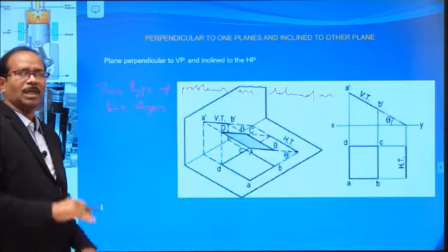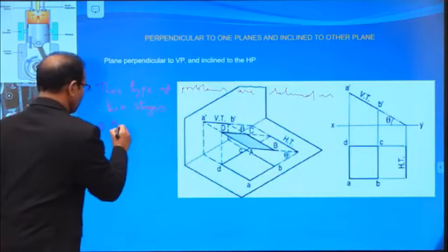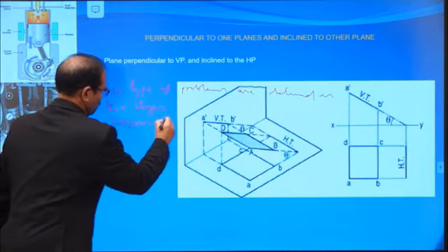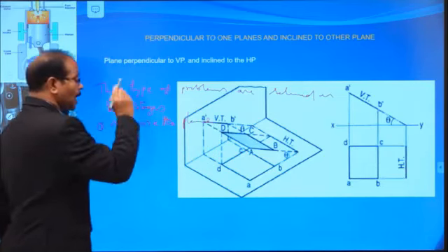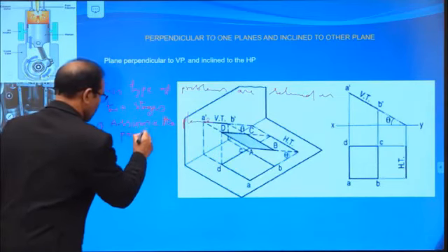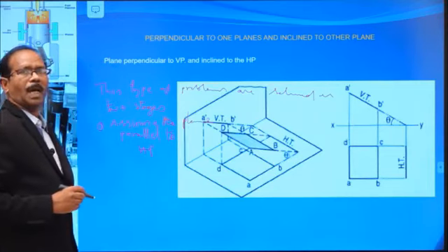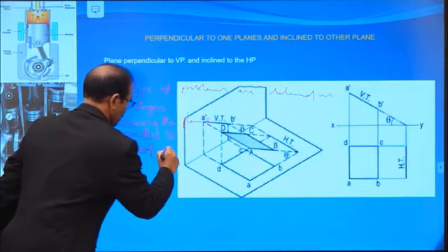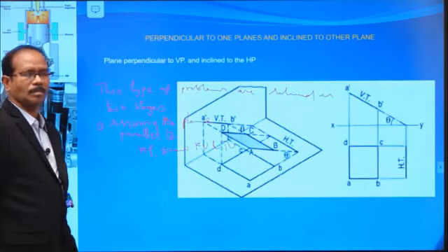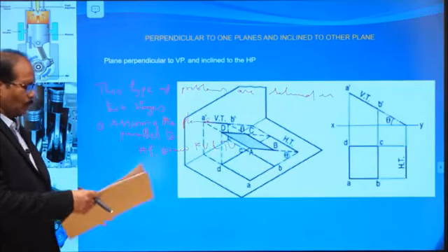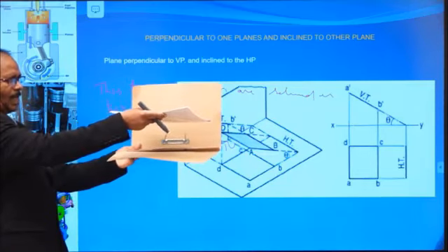Such type of problems are solved in two stages. First stage, assume the plane parallel to that reference plane, parallel to HP, and draw the front view and top view. So parallel to HP, first draw the front view and top view.